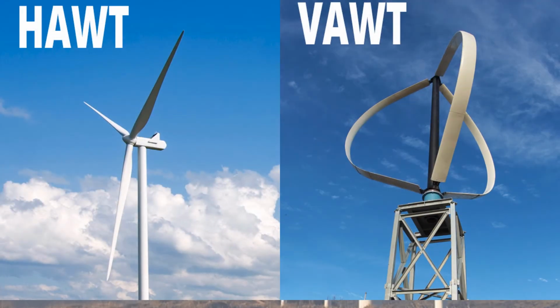In HAWTs, the rotating axis of the wind turbine is horizontal or parallel to the ground, whereas in VAWTs, the rotating axis of the wind turbine is vertical or perpendicular to the ground. HAWTs are primarily used in big wind applications, whereas VAWTs are used in small wind projects and residential applications. One advantage of VAWT over HAWT is that it doesn't require a yaw mechanism, since it can harness wind from any direction.